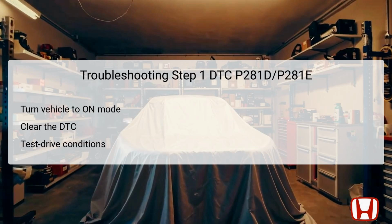The first step in diagnosing DTC P281D and P281E involves establishing that the issue is confirmed and then performing a series of preliminary checks. Start by turning the vehicle to the on mode, which activates the electrical systems but keeps the engine off. Following this, use the Honda Diagnostic System, HDS, to clear any existing DTCs.